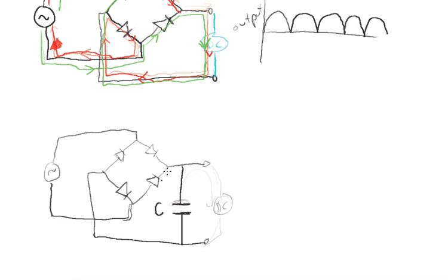This discharges, and then of course when the current flips and starts to come back on, it starts providing the DC current through here and starts refilling the capacitor back up. And then when the current starts to flip off, the capacitor discharges and keeps the current going. And then when the capacitor starts to run out, this goes back up on an upswing and starts refilling the capacitor and keeps the DC current going.